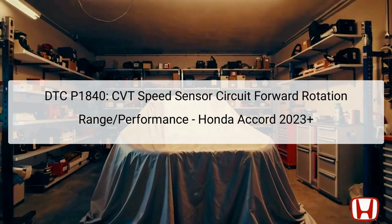DTC P1840, which stands for Continuous Variable Transmission, CVT Speed Sensor Circuit, Forward Rotation Range, Performance, signifies a potential issue with the performance of the CVT speed sensor in the Honda Accord 2023 model. The CVT uses a speed sensor to monitor the secondary shaft's rotation speed, which is crucial for efficient transmission operation.